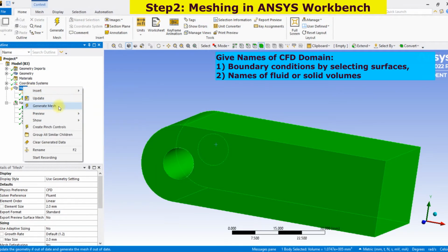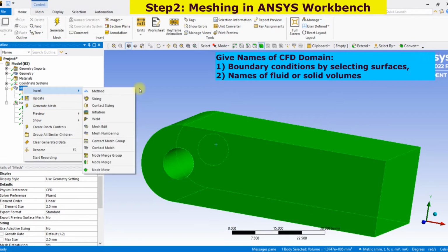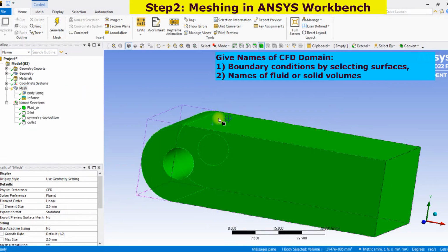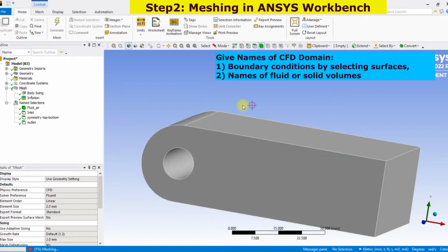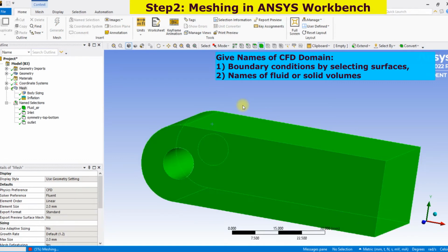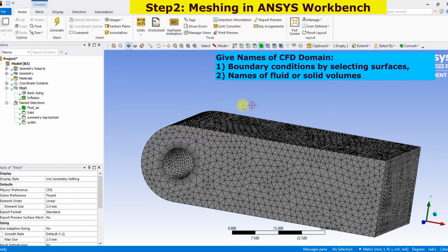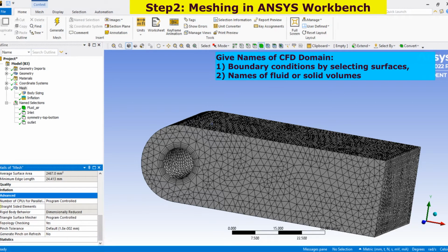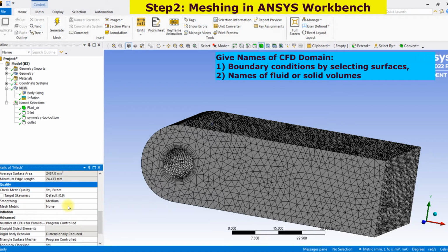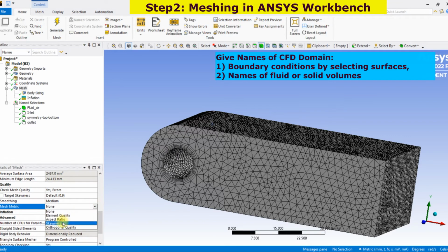If you think the mesh is too coarse, check the size. This size is very small, and you can check the mesh quality. And yes, here skewness is 0.79. That means it is around 0.8. Check the quality. Check quality is okay. That means we can use it for the plane. And the maximum skewness allowed for the plane is 0.98. That means this mesh is okay.